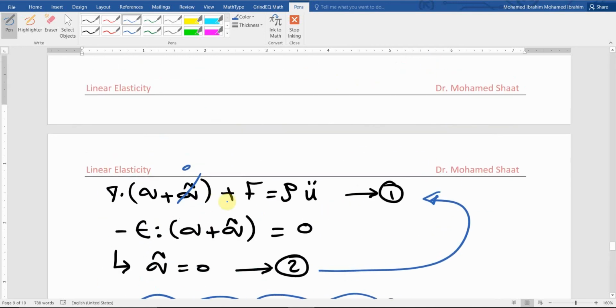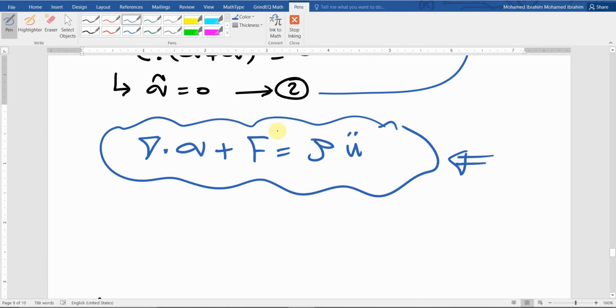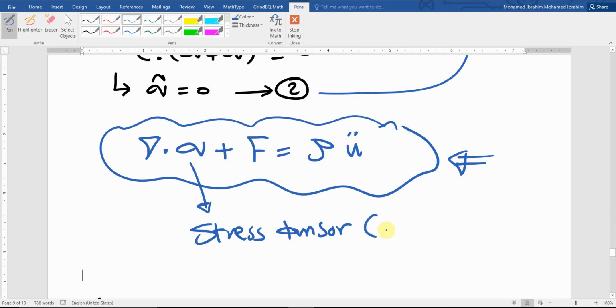But what I've demonstrated here is how we derived these equations of motion, starting from the mechanics of a discrete system of particles. Make sense? And that's what we're going to consider through the linear elasticity class: this sigma is the stress tensor. This is the stress tensor that you had experience with in the mechanics of materials class. All the stresses that you considered in that class were sigma. This sigma is a symmetric tensor.